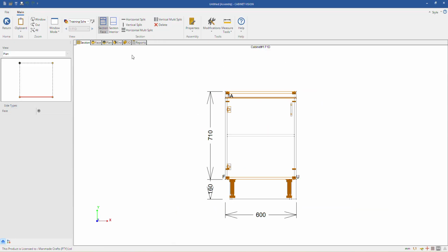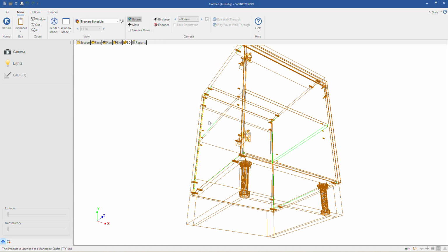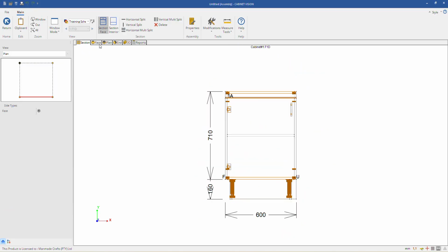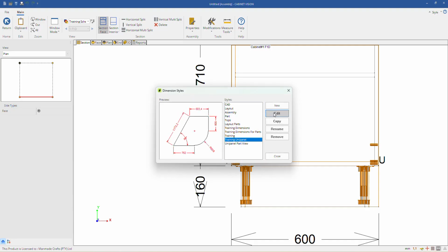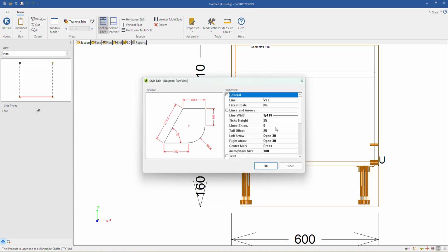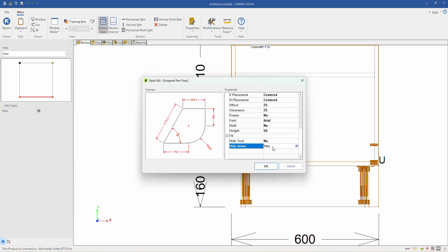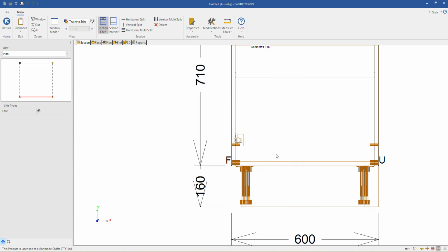I just want to check something. On the feed, how come it's just showing the one arrow? Because we never set it. You see where it's got the 160? It's overlapping. So that's where you have to activate and deactivate. You remember there in the dimensions where we said here, training unipanel go. This one, edit, hide arrow, yes or no. So that one is okay.